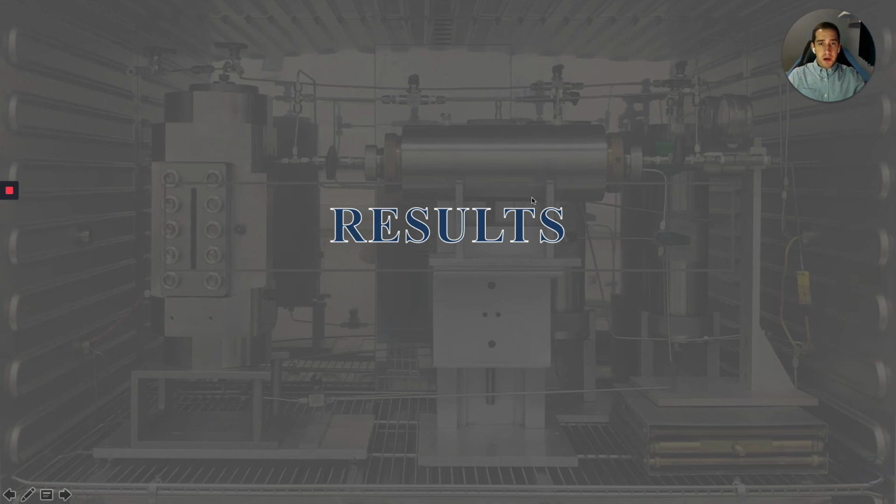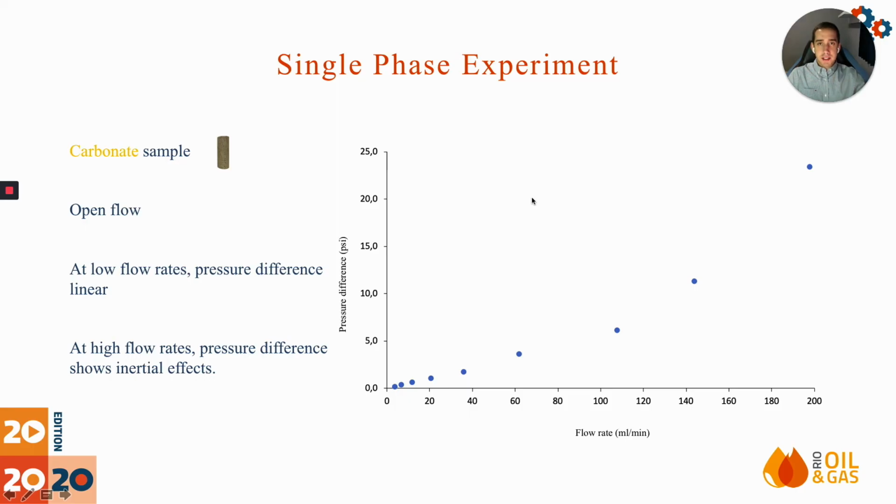So now I'm going to talk about the results that we got. This is the single phase experiment that we ran to check if we built the experiment correctly. We chose the carbonate sample to do it, and it's an open flow, so the reducing valve was not set, so we have only gas during the whole experiment. At low flow rates, we got a linear pressure difference, as we can see, and at high flow rates, it was no longer linear due to some inertial effects.